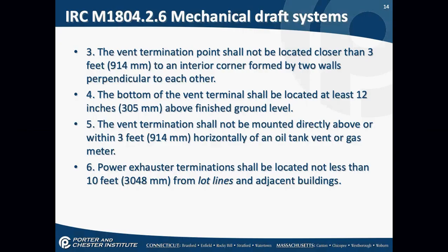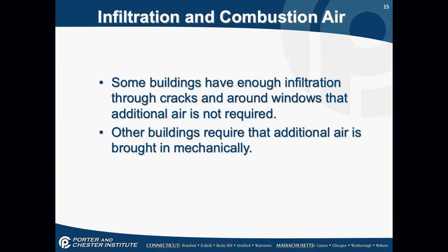Now, combustion air. That's the air my equipment is going to use as it burns. Some buildings have enough infiltration, that's air coming in through cracks and crevices around windows, that additional air is not required.